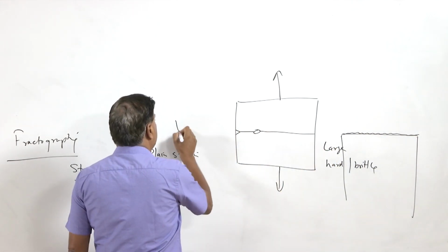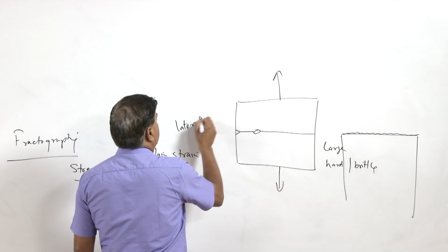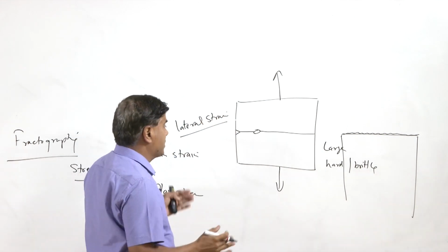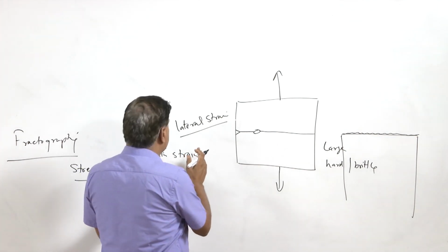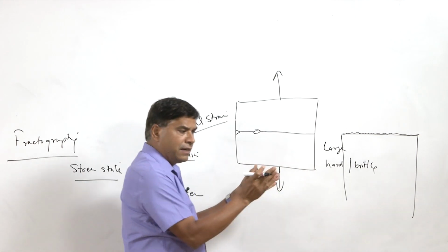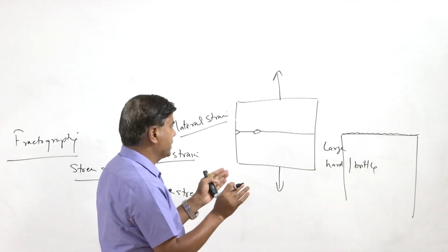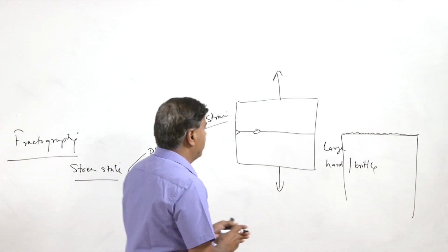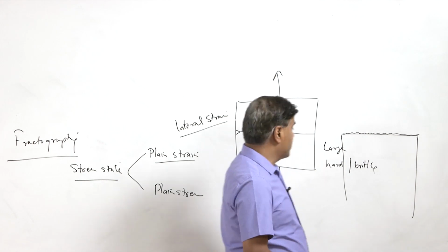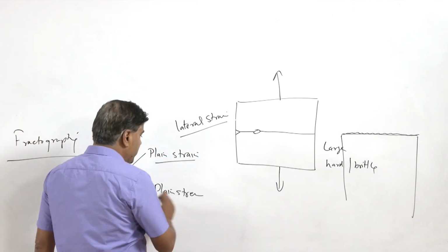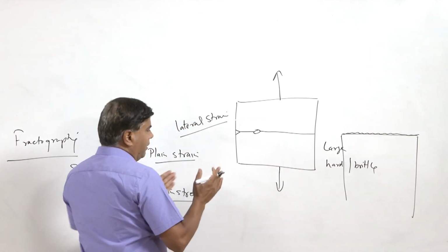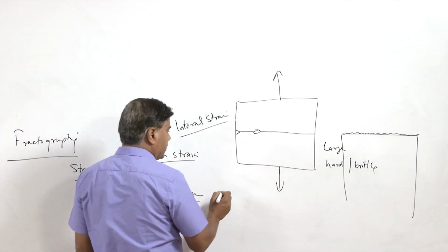Since there is no lateral strain in the component due to the external loading, this is the situation where the plane strain condition exists, and there is no thinning, necking or reduction in cross sectional area. The fracture surface will be the typical square one, perpendicular to the external loading, while plane stress conditions involve a lot of lateral strain and reduction in cross section.